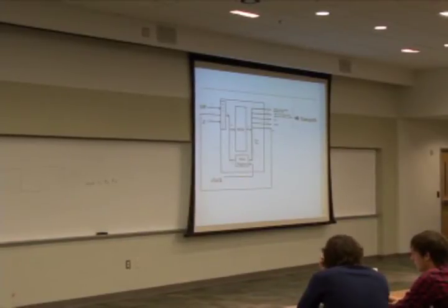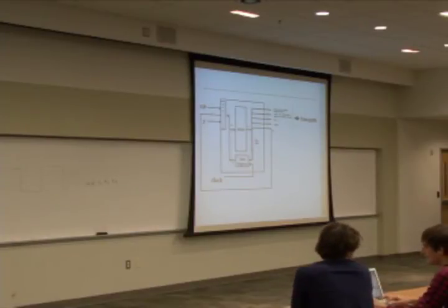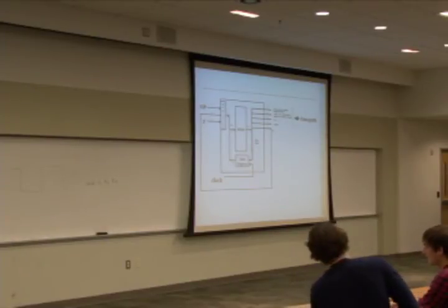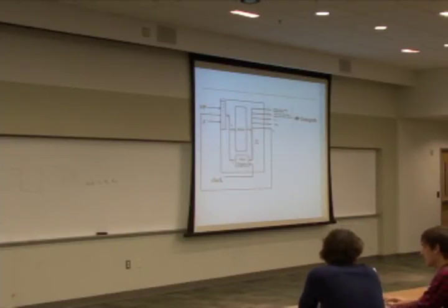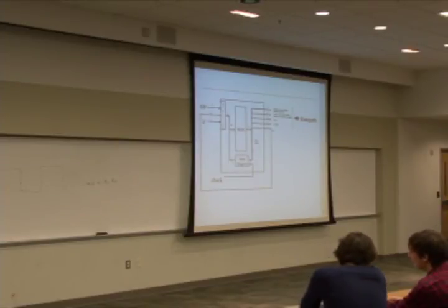I noticed there are like 10 bits going into the ROM and 24 coming out. Mm-hmm. So the 10 bits kind of say what instruction I want to get out, and the 24 at the end actually give the individual control signals I want. You can think about this as a pointer to the stack. Like, okay, this is the address I want to read. So you have 10 bits for the address, and then the ROM has probably 32 bits available, but we are using only 24.